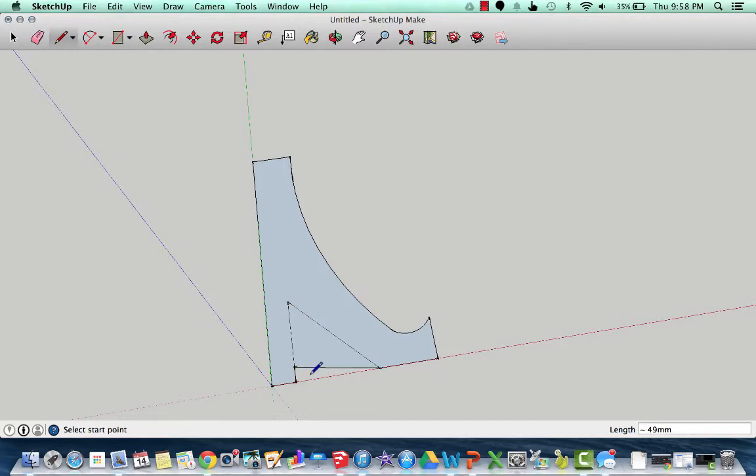For example, if I were to print out this piece here, it's going to have a hard time because there's nothing for this layer to build on from this layer here and this layer here and so on. So it's going to sag a lot. You're going to get a lot of extras that you don't necessarily want. It's not going to look very appealing. Whereas this piece here, it's at about a 45 degree angle, and it has enough on the layer below it that will build and mold with the layer above it. So just keep that in mind as you're designing it and as your students are designing it as well.